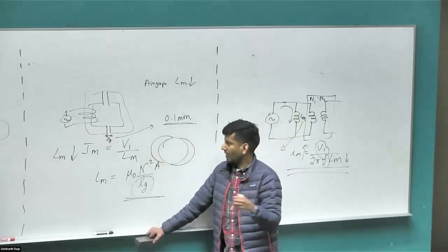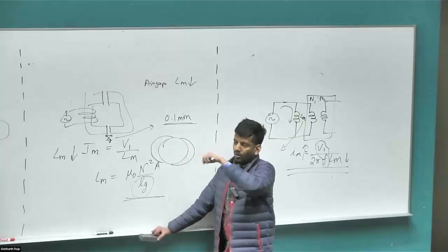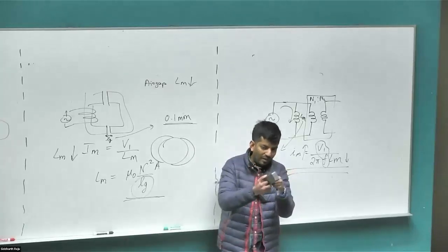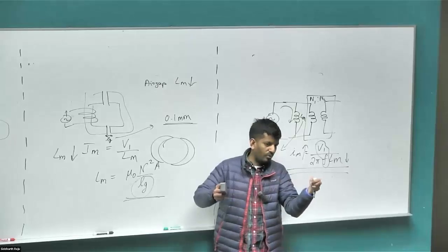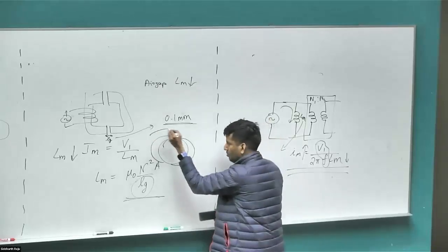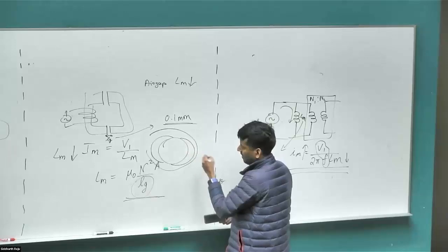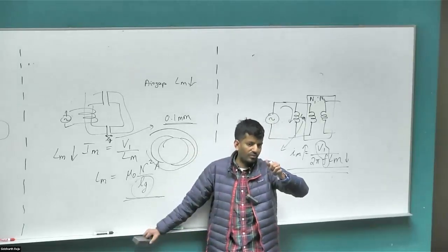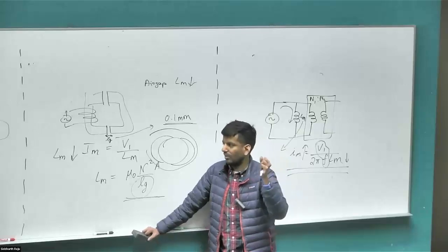There is a second one, where these magnets are basically stuck onto the rotor with some glue. As the rotor starts to rotate, the magnets are going to experience a centrifugal force that is going to pull them out. If the air gap length is so tiny, then these magnets will start scratching against the stator as the rotor starts to rotate too fast. And magnets being brittle will crack instantaneously.